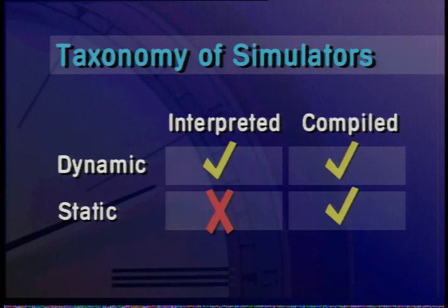We should note that there is a significant class of simulators which are static. That is, they don't use dynamic scheduling, and they don't have event routines. They simply order all of the evaluation elements, typically gates, in rank order from input to output on clock boundaries, and on each clock, all gates are evaluated in turn. This leads to very fast gate evaluation. However, it has the obvious disadvantage that all the gates in the entire model get evaluated every clock cycle. They also have the disadvantage that these have been limited to synchronous designs, and sometimes level-sensitive designs. These simulators also don't deal with asynchronous feedback loops, which is a problem, though it is of diminishing importance.